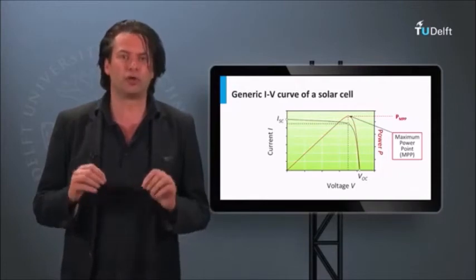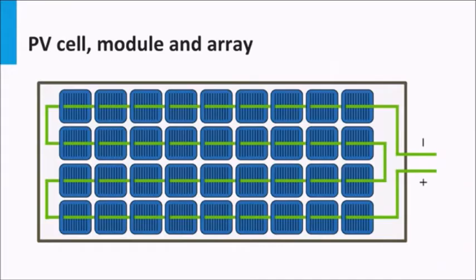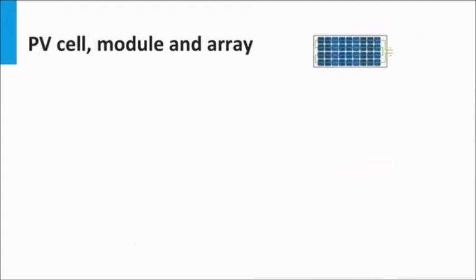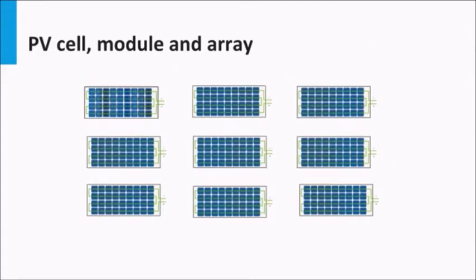For reasons discussed before, the solar cell has an IV curve as shown in the figure. As a quick recap, you might remember how the IV curve of a PV module is similar to that of a single solar cell, as the PV module is merely an interconnection of several solar cells. A series or parallel interconnection of cells increases the voltage or current respectively, but the overall nature of the IV curve remains the same. In a similar manner, it can be said that the interconnection of the PV modules to form a PV array would yield comparable IV curves, albeit at different IV levels. Thus, it's reasonable to consider the IV curve of a solar module or array similar in nature to that of a solar cell. So let's head to the simple IV curve of a solar module.